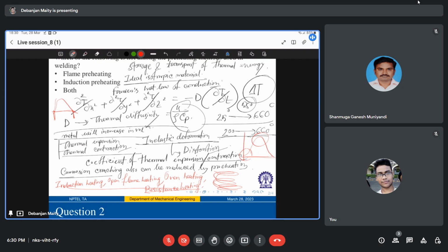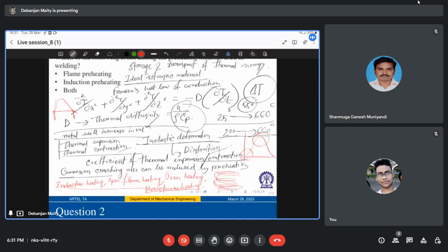What is much easier, welding steel or welding copper with resistance spot welding? Of course, steel will be much easier because the electrical resistance is higher for steel, and it cannot dissipate heat as quickly as copper.